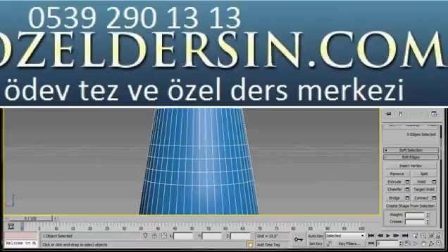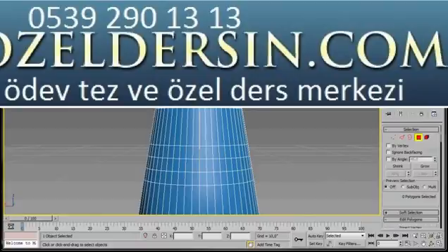So let's go over to the panel and select the polygon mode, then come back and click on this polygon. Hold the Control key down and we're going to select the next polygon, the following, and that one on that side. We're going to do the same down here. This will be the end of our handle. We want 4 polygons, holding the Control key down all the time.